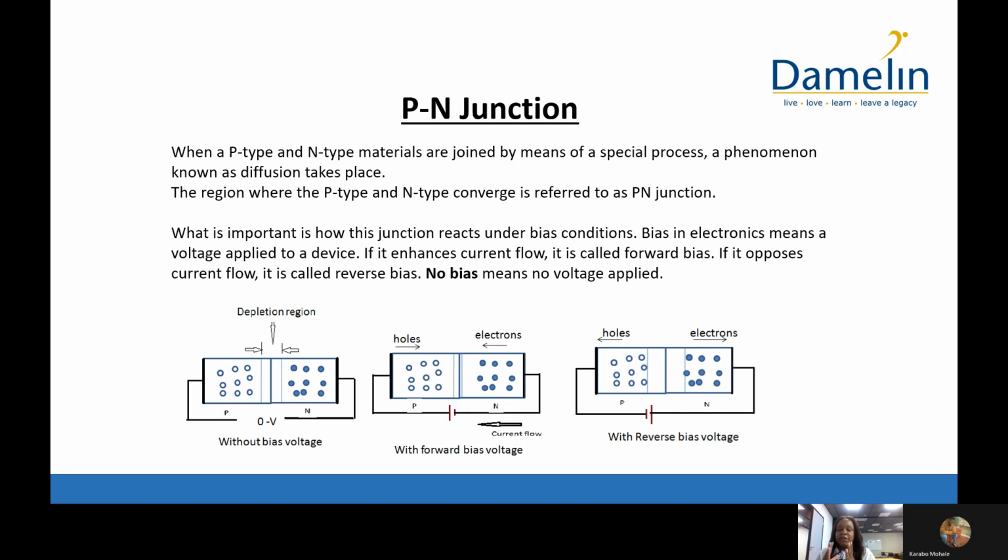This moving towards the junction is making the junction smaller. So that's why when we forward bias, we have a small junction. Okay, and you can notice that because they are both moving towards the junction, the p-type is attracting the electrons from the n-type, and they are going through the junction easily with no problem. That is why when we forward bias, we make the semiconductor act as a closed switch. Okay, because the current flows easily through that depletion region from one part to the other.